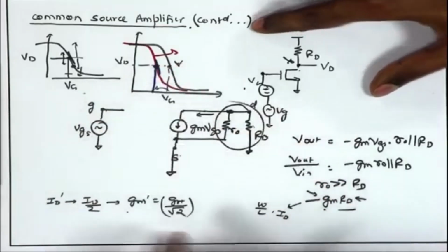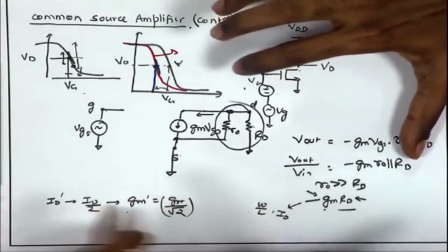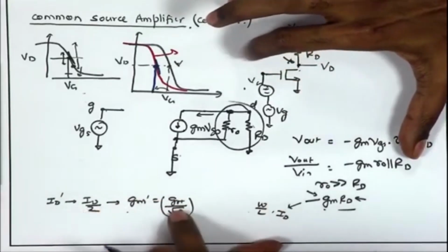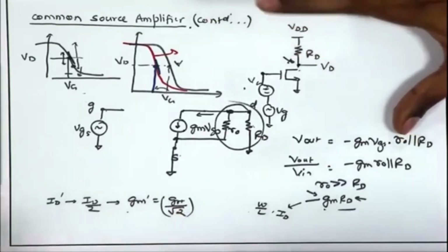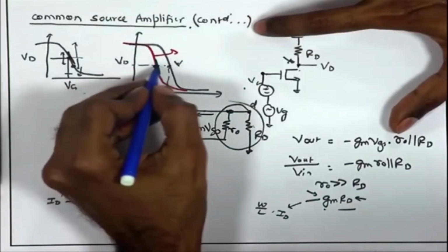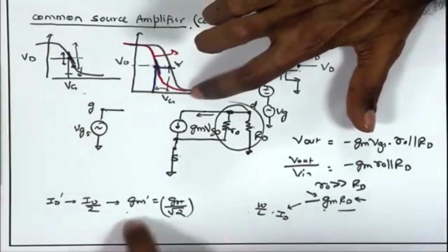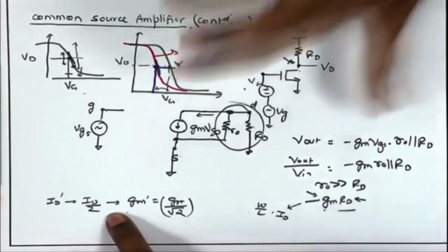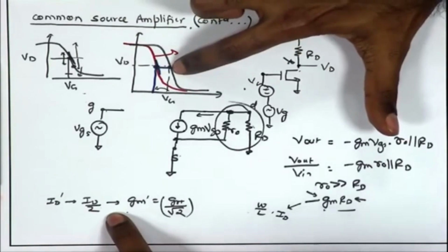So, what we are trying to do is play with the DC bias current and the resistance to increase the gain while maintaining the required signal swing. Remember, the target is that we should keep the DC bias point midway between the two extremes. So, we reduce the current to half and increase the resistor by double, so that the DC point at the output is the same.